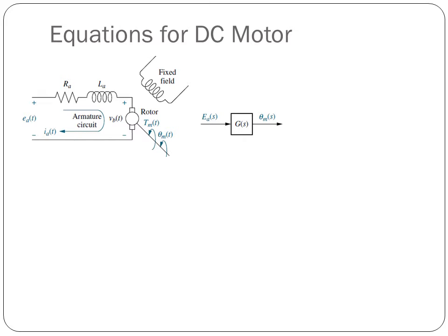So when considering the motor, we have already learned this type of circuit for the DC motor system, where we have an electrical input to the armature of the motor, and there is an armature resistance, inductance, and when the rotor moves, proportional to the speed of the rotor, there is a back EMF Vb.